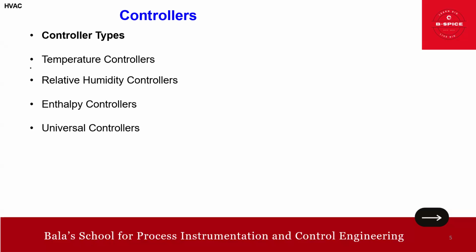And of course, other input variations are also available like 2 to 10 volt DC and also 0 to 20 milliamp signal. Because these inputs can represent a variety of sensed variables such as current like 0 to 15 ampere or pressure 0 to 3000 psi, the setting and scales are often expressed in percentage of full scale only. So basically, this is a universal controller, friends.